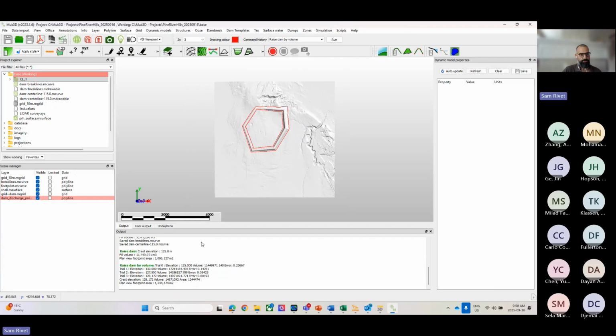You can see here in your output window, it went through a couple of iterations to get there, namely 3. Well, I guess 4 if you count trial 0. So it started at 125. I was like, okay, no, I have material left over. Then it went to 130 because you defined it to step through in 5-meter increments. And then, okay, well, our results are going to be between 125 and 130. Let's try 127.5. And then finally got to 128.172. And that was the appropriate guess given the error tolerance that we set.